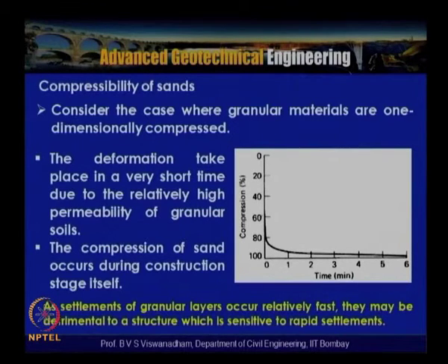In this particular slide, the time versus compression of a sand is given, and you can see that within a fraction of a few seconds, the sand has undergone 80% of compression. That means the settlement of granular soils takes place very instantaneously. If the granular materials are one dimensionally compressed, the deformation takes place in a very short time due to the relatively high permeability of granular soils. The compression of sand occurs during the construction stage itself.